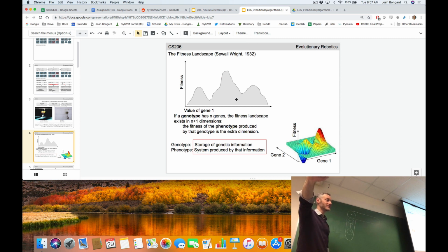So we have a very simple robot: two objects, one joint, two neurons, a sensor neuron and a motor neuron, and one synapse with one synaptic weight. If I want to alter the behavior of this simple robot, I can alter this single number, and it will alter the way that the joint rotates relative to what the touch sensor is sensing.